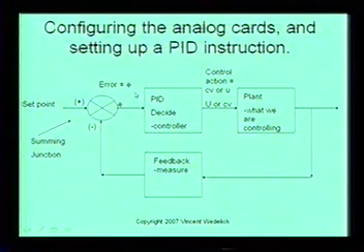So, you know, what you see here is you see a rise to your set point, then it comes down, slightly goes below your set point, and starts settling down on your set point and stays right there on your set point. So this will continue to go back and forth until the set point is equal to the measured value, or more importantly, the measured value is equal to the set point, because if these are equal, then error is 0, and then the PID just says, okay, I'm good. I'm exactly where I need to be. I won't make any more changes.